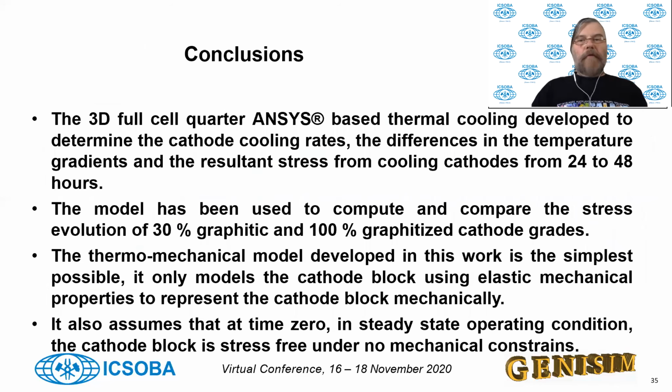Conclusion: we have developed a cooling model, and we have analyzed with that the crack formation, well, the stress prediction, for two types of cathode grade, 30% graphitic and 100% graphitized. The mechanical model is very oversimplified, but we have to make some assumptions to be able to compute something.